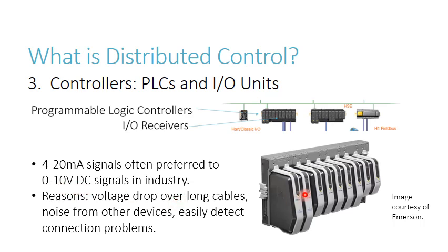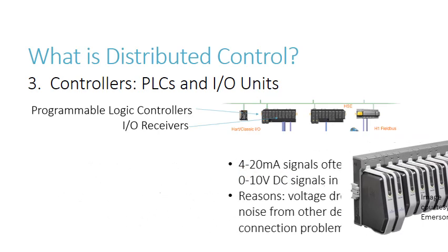Likewise, if you had an open circuit, the I/O unit would be seeing some sort of floating voltage, maybe with a little bit of noise around 0 volts, whereas your wire's been cut and is just hanging in space, but you can't really tell because you're seeing something that is not that unusual. Whereas with the 4 to 20 milliamp signal, if your line gets cut and you're seeing zero amps, then you know that there's a cut in your line. So these are reasons why the current is preferred.